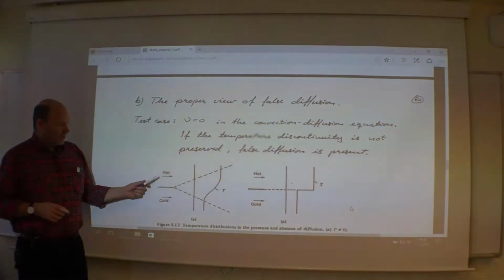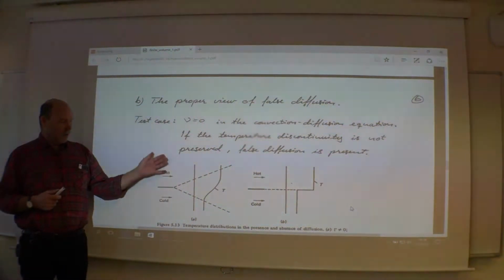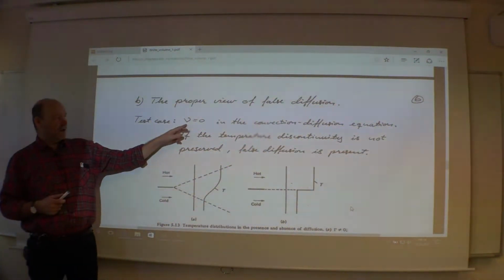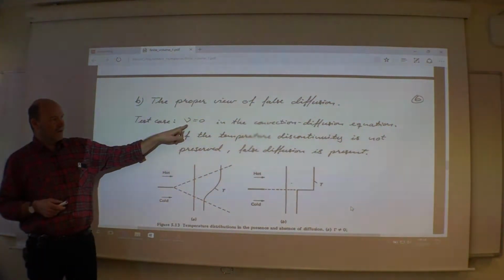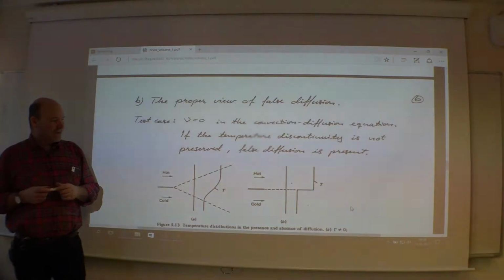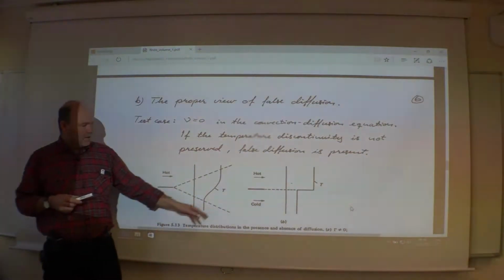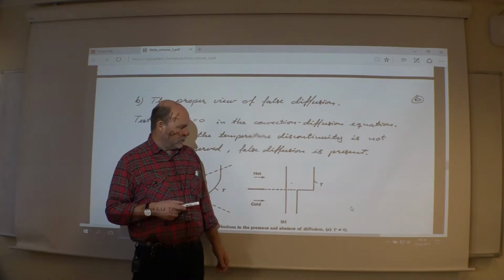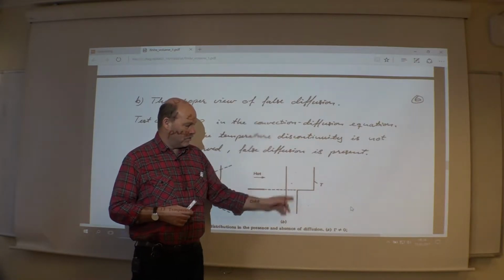Meaning if you have a problem like this, you send in a constant velocity, and then you have hot and cold fluid, then they actually shouldn't mix. You don't have any diffusion mechanisms. If it's temperature, of course, it's not viscosity, then it's the little k, thermal conductivity. And if that one is 0, you shouldn't have any mixing at all. This should be the correct solution for all times, for all spaces, when the flow goes to the right. So you should keep this sudden jump.